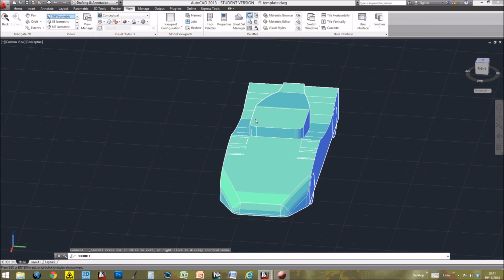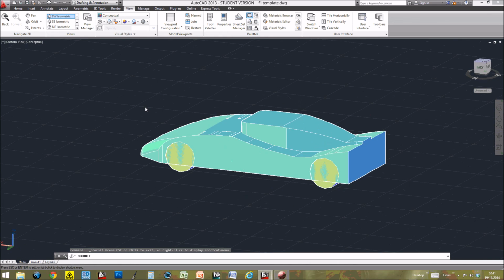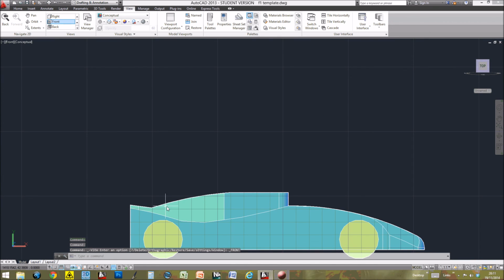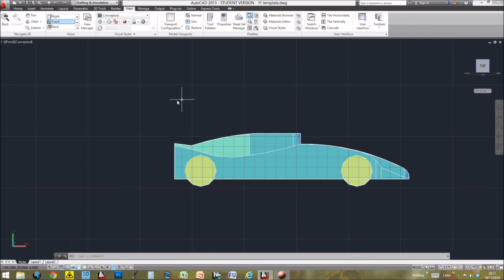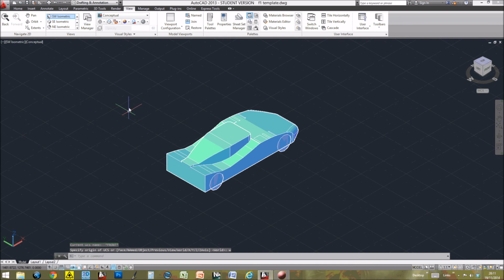So, with a little bit of thinking and chopping, you can actually create some quite powerful aerodynamic shapes. If you wanted to, you could even draw a rear spoiler by going into your front view, drawing your spoiler shape and extruding it 85mm. That gives you a bit of a rough guide into how to set up and use Autocad to design your shapes. Have a go, see what you can come up with. Those of you who are feeling really adventurous can try using the loft command to create your car body shape.